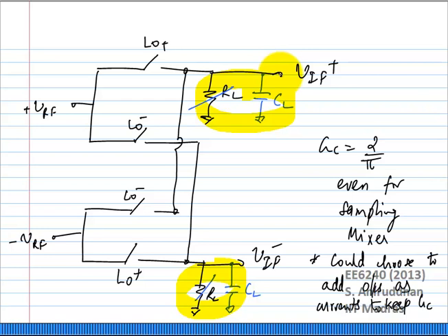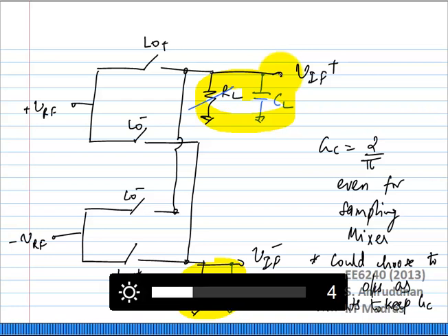important thing to note is that because the circuit is time variant, the input impedance, looking in impedance as seen with a voltage source and as seen with a current source are different. When you have linear time invariant circuits, obviously the input impedance is independent of whether you try to drive it with a voltage source or a current source, but unfortunately in this case it is not the same. Okay.